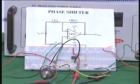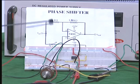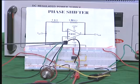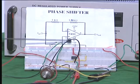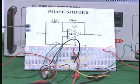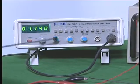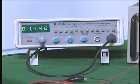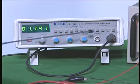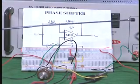I will just show you the demonstration of this phase shifting amplifier. Now, you observe the circuit. I have a 1K here and I have a 1K here, R prime as I showed in the picture, and this is a potentiometer, and I have a capacitor which is about 0.22 microfarad. So, the input here is from a function generator with a sine wave oscillator output. You can see the function generator to the left of the screen. I have chosen some 1 kilohertz as the frequency, 1.14 kilohertz, and the output is connected at the input of the amplifier here, and the output of the amplifier is monitored using an oscilloscope.